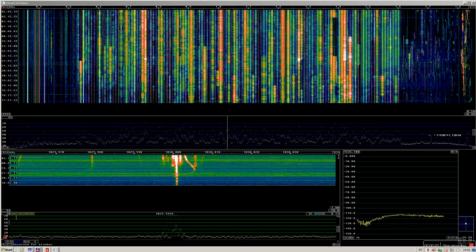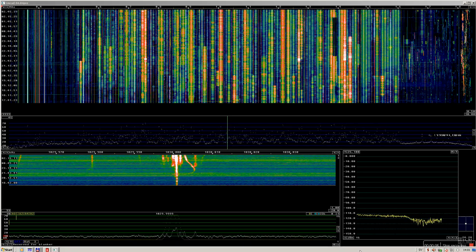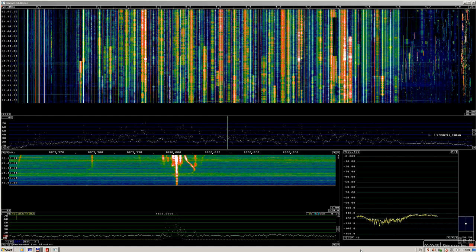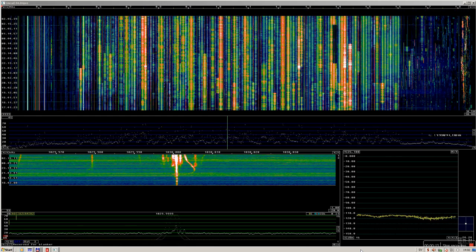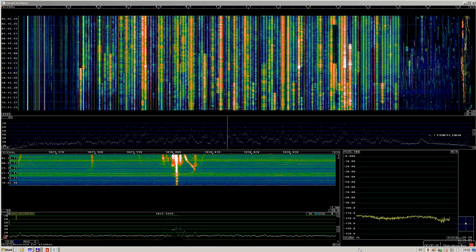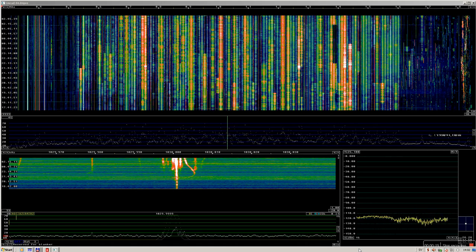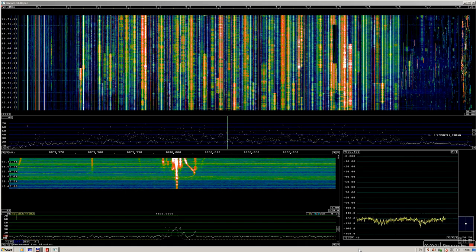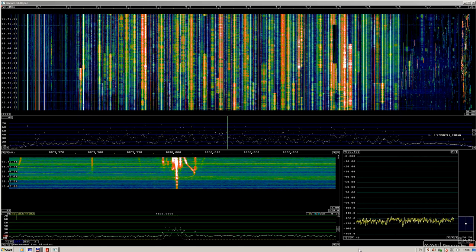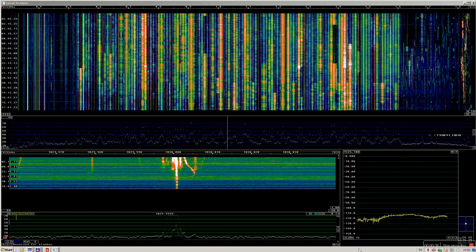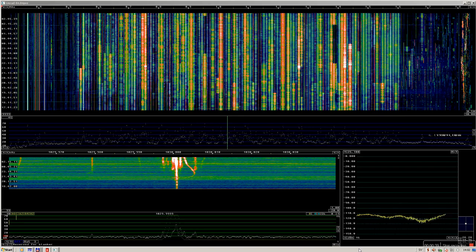So we can see from the baseband waterfall how the sun is setting over the United States and maybe Canada or somewhere else, I don't know, and making the ionosphere thinner so the medium wave signals can reach here. I'm about 100 kilometers west from Stockholm. We can see stations 20 hertz below and maybe 40 hertz below the nominal frequency 1030, and many stations within just a few hertz.